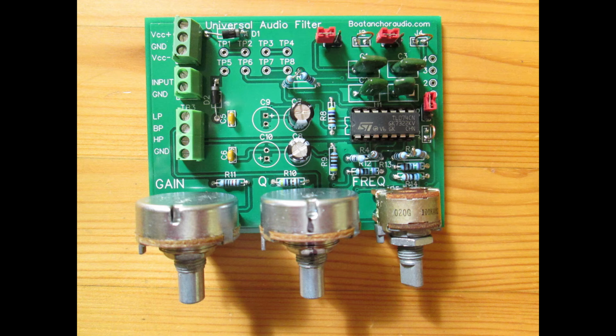Okay, we went over the schematic of the filter. Here's a picture of it. I'll go through it very briefly. On the extreme left, we have a pot. That is the gain control. In the middle, there is another pot. That is the Q control. And on the far right, there is the dual pot that controls your frequencies. You'll see the input terminals for voltage, input for audio, and the 4 terminals for output, of which we're only using 2, namely the ground and the bandpass filter output.